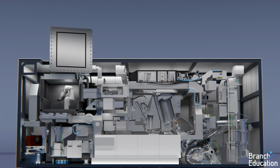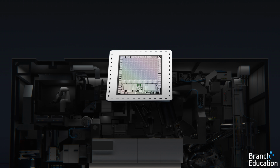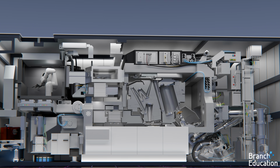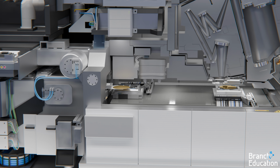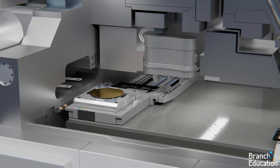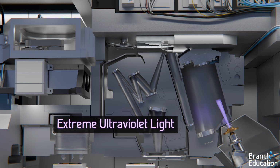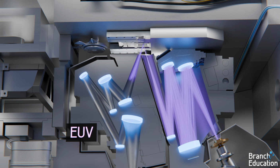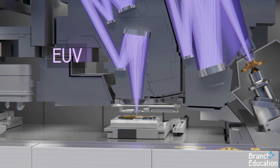To start, the EUV lithography machine takes the design of a single layer of a microchip on what's called a photomask and loads it into the machine. Next, a 300mm silicon wafer with a set of prior processes applied to it is placed onto a wafer carrier inside the machine. With both in place, the machine uses extreme ultraviolet light, or EUV, and a set of mirrors to copy the design from the photomask onto a silicon wafer.